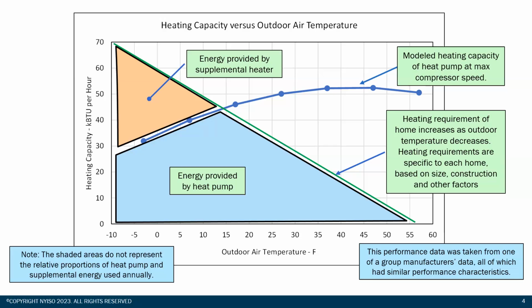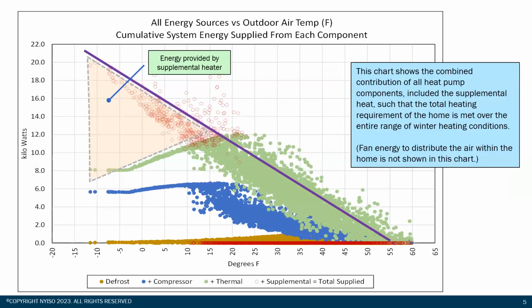Now, for a 5-ton system, this is what you have. If you are going to match the capacity of today's gas furnaces, you would need two 5-ton units. So you can eliminate the orange supplemental heating for a heat pump if you go to a 10 or a 12-ton system. That's the theoretical performance. Now you see what a building load model from DOE2 provides.